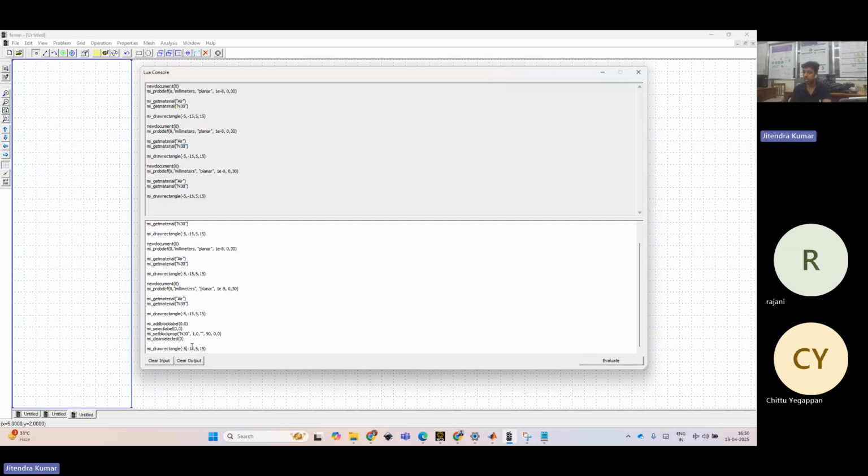You could straight away take minus 50. Y is also minus 50. Any bigger air, however you can create, that should not be an issue. 50, 50, 100, 100, whatever value comes to your mind, you could create. Right. So it is a 100 mm air boundary. Okay. Now again, we have to assign air material also, right? We have to do the same thing, assigning.